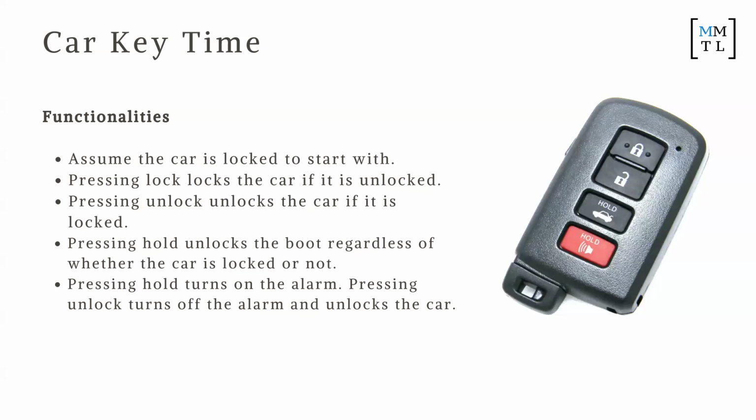How to get out of here again. It's a state that you can never get out of. And then it would be like this. Wait, where is it? Close boot. Yeah, close boot. Physically closed, but that's either unlock or not. There could be two transitions, yeah, that's right. So as you're making states, make sure there's a way to get out of all the states, right? There should never be a terminal state for the car.